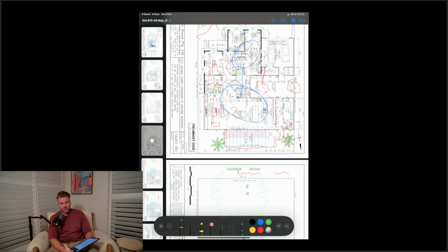But thinking three units, so we're thinking a 14 kilowatt for this space here. So this will do that there. So that whole background floor area, especially in summer when we're getting the northern light in and that heat, we're able to control it. This southern side is going to be a 10 kilowatt at the front. So that's a 10 kilowatt there, 14 kilowatt there.